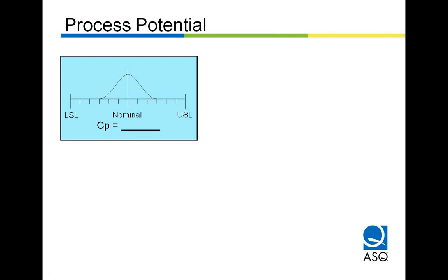And then I made my specifications, because I like Six Sigma, 6 standard deviations plus the mean, and 6 standard deviations subtracted from the mean to set my specification limit. So whatever the value of a standard deviation in this graphical interpretation, it's 12 standard deviations, that's the tolerance, the maximum variation from the upper spec to the lower spec, divided by the 6 standard deviations. Well, 12 divided by 6 is 2.